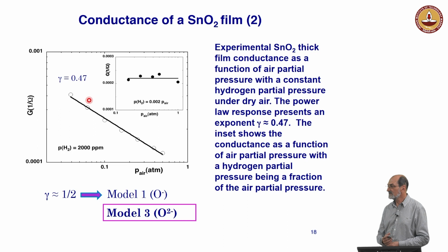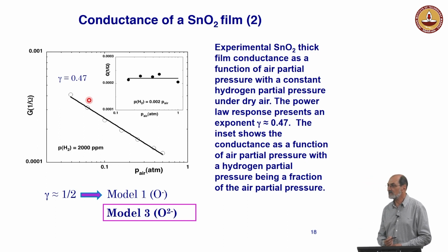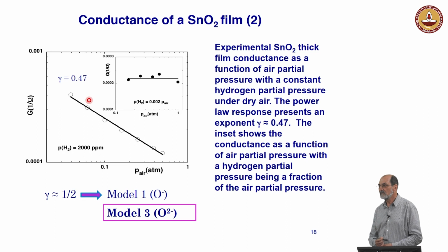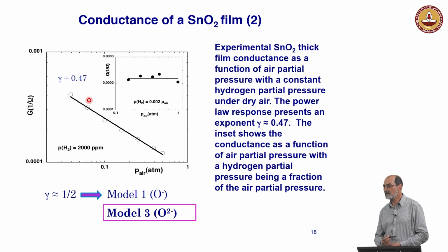And the second question is, if you are doing this with a p-type oxide, will it just be a flipping over of the analysis, or is it not so simple? I think the analysis in principle should be the same, it would be symmetric. But we should check it. We never did experiments. We are doing tin oxide because it's the most popular oxide used in gas sensing. We should check it with zinc oxide. I think that would be a good first.